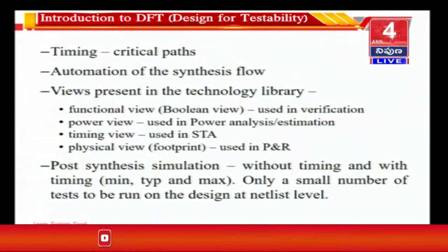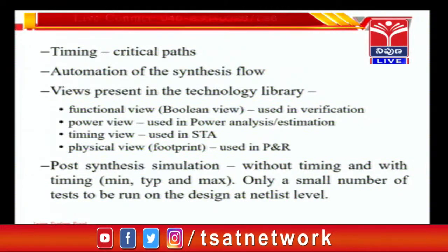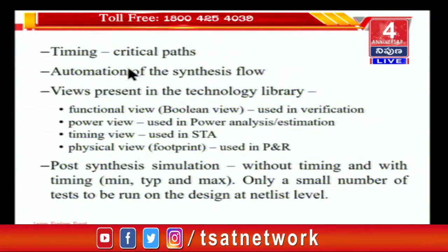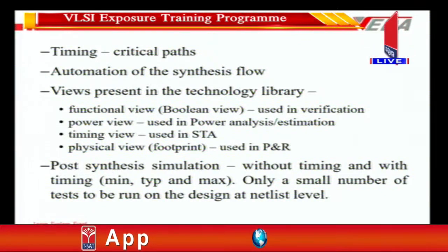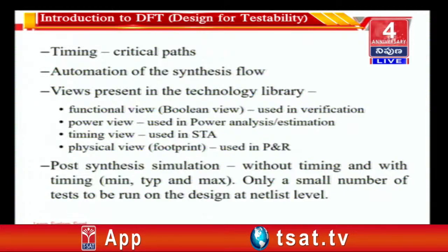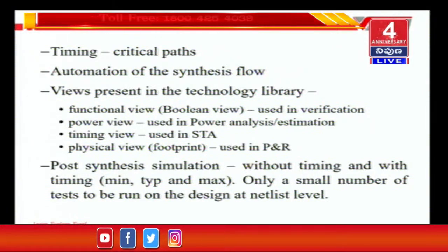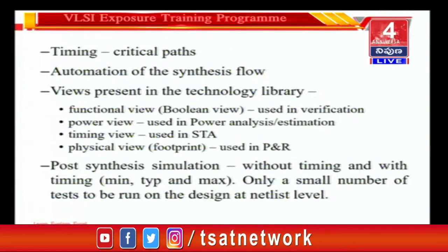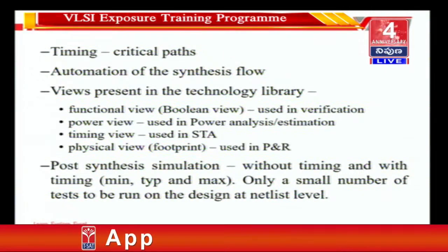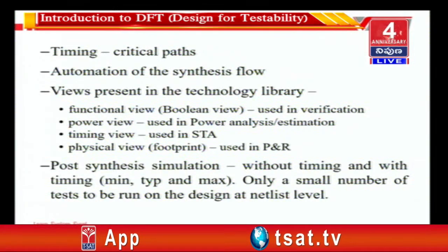It is important to automate the synthesis flow also, and therefore scripts are written for the synthesis, so that once the design is given, the whole thing gets automated. And if there are certain types of names that have to be avoided by the synthesis tool, then we can give our own names to the outputs, saying that this output must be appended by a particular string or something like that, which can be done in the synthesis tool.